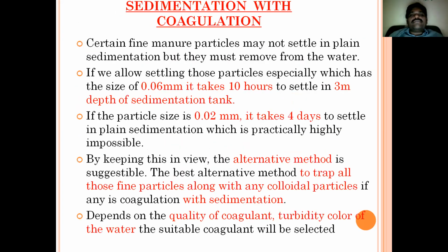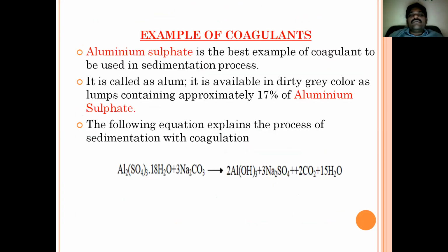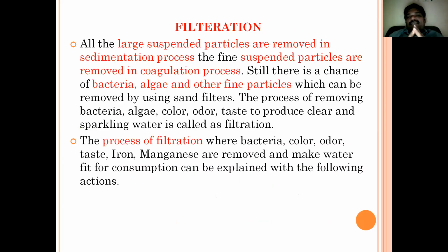See here, filtration. Before that, what is the need for filtration, we'll discuss now. In the sedimentation process, all the heavy particles settle and are taken off. In the next step, the fine colloidal particles are also removed by adding coagulants.